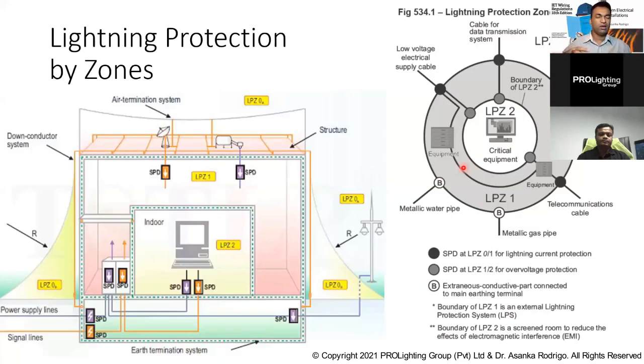Earlier, even if there was a minor voltage disturbance or overvoltage, our equipment was able to manage that, because it was robust and its insulation was very high. But nowadays equipment is not like that. For example, a classic example: earlier we were using incandescent lamps, but all of them were replaced nowadays by electronic LED, where even a minor lightning surge can damage our lights. Because of that, transient overvoltage protection nowadays has also become a mandatory requirement.